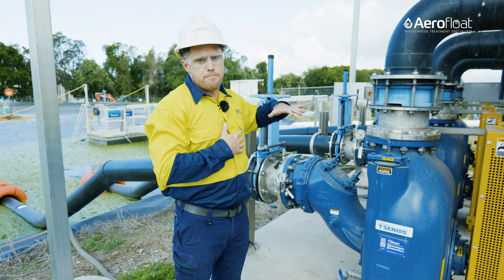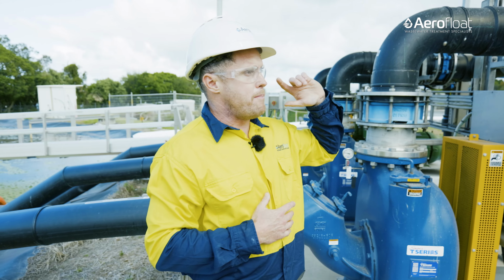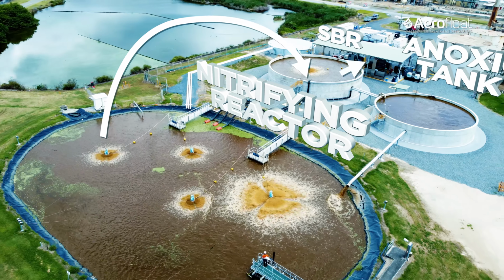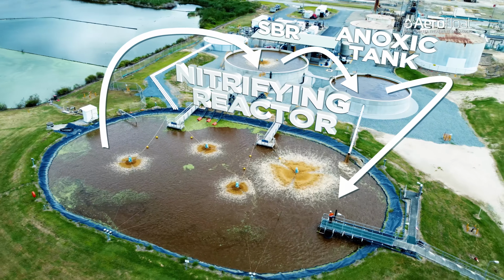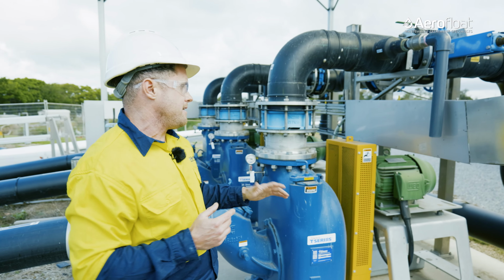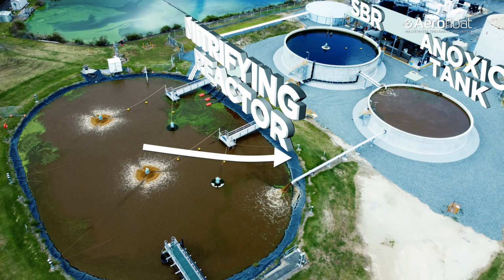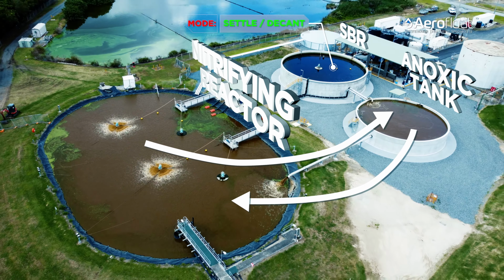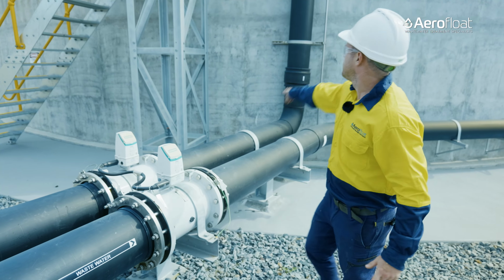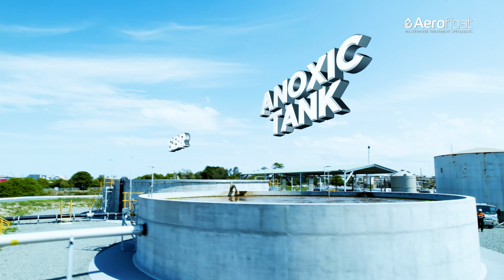So here we have 3 pumps. In normal operation outside of settle and decant, we're pumping to the SBR, overflowing to the anoxic tank, and then back around to the NR. When we go into settle and decant, this third pump will kick in and pump from the NR straight to the anoxic and back, and then the SBR goes into settle and decant. So you can see here we're either pumping to the SBR or we're pumping to the anoxic tank.